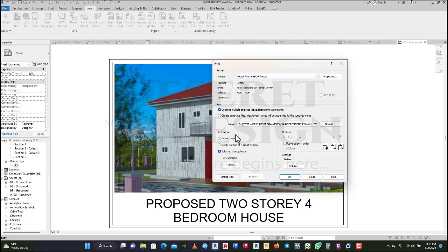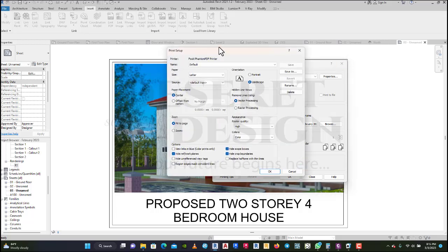So in AutoCAD, when you want to print, everything you want to print, you come and select and print it. Do you get it? But here, they've done it simple. First of all, we also need to set the page. You need to set it up. So you go to your setup, the setting, then you need to choose the paper size you want to use. So here we'll go into our paper size and look for our A3. Then when you pick your A3, the orientation is mostly set to landscape, unless you want it otherwise.